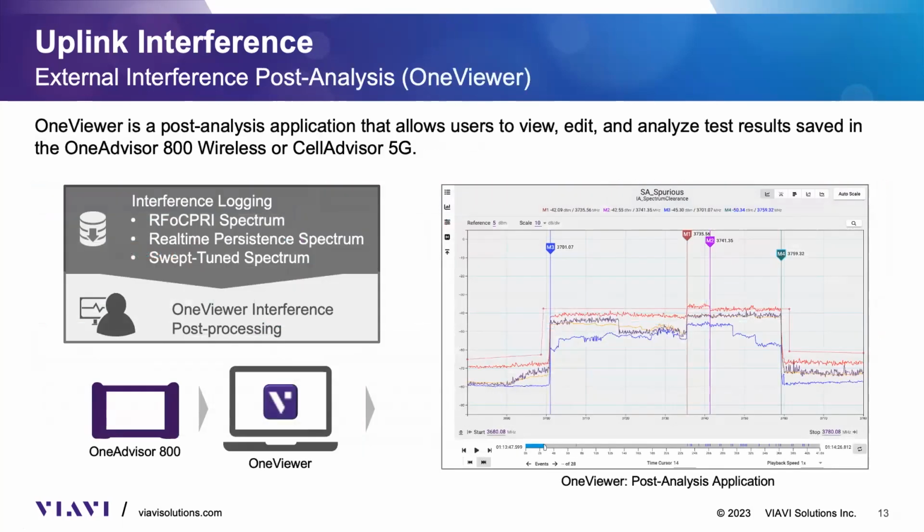Okay, so in terms of a time domain aspect, sometimes those interferences can be intermittent, meaning that they're not there all the time. So the best way to analyze those intermittent interferences is basically to log the spectrum. We can leave a device there just to assess.